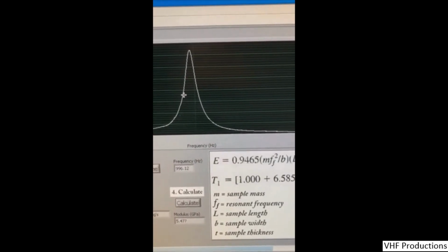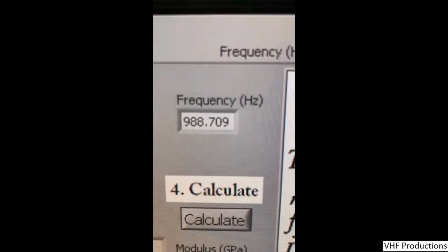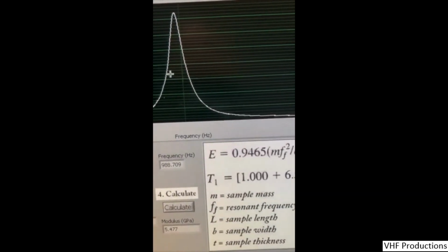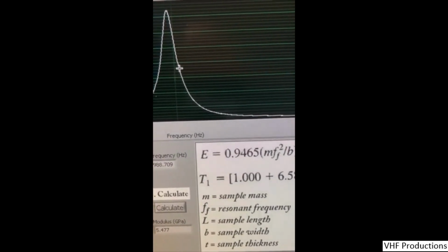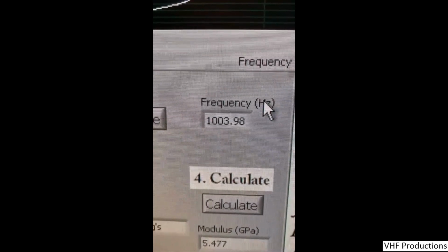We will also be determining the min and max values of the full width of half maximum positions on the frequency spectrum on either side of the resonant frequency. That will define the frequency bandwidth to be used to calculate the Q factor.